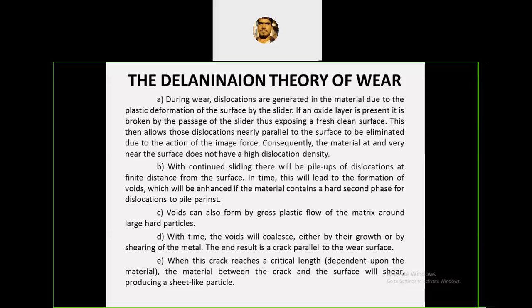Second thing is one point. Because of the plastic deformation, one small point of voids will start propagating. It is just one point, like this. Because of continuous operation, the load, the speed, the environment, that small point will start to propagate and increase in length.